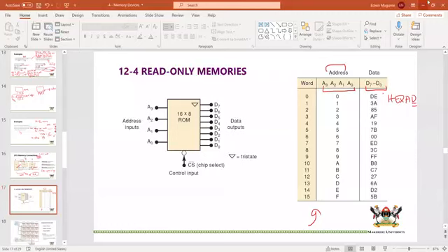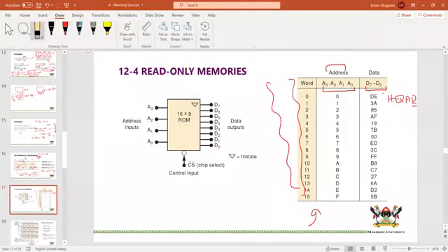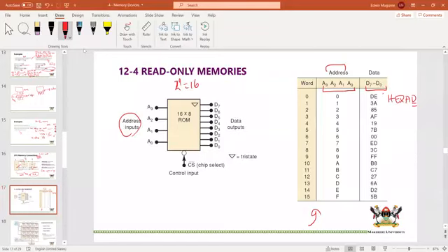I think you remember hexadecimal, but there is a part of a table here that I didn't include. So if you're worried about hexadecimals, you'll still be able to find a normal binary table. Because you have 4 address bits, it means the words are 2 to the power 4, which is 16. And so this is a 16 by 8 memory. And it is ROM.